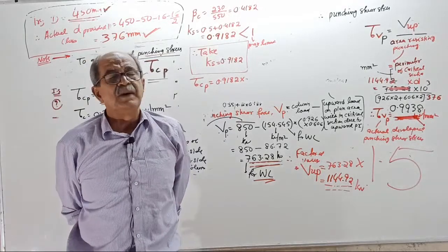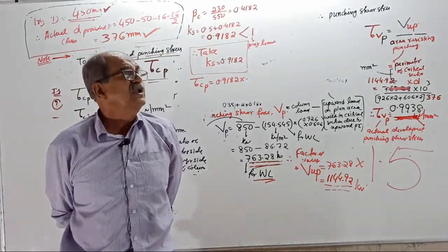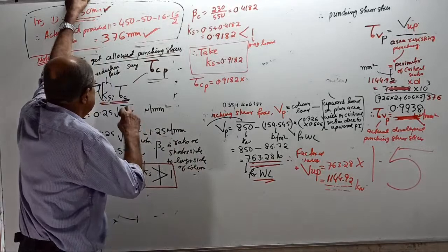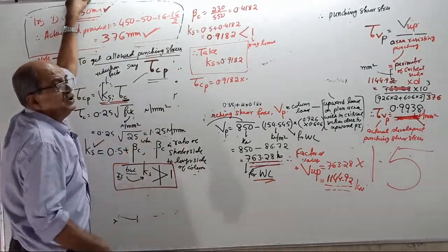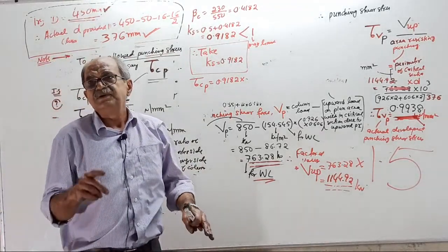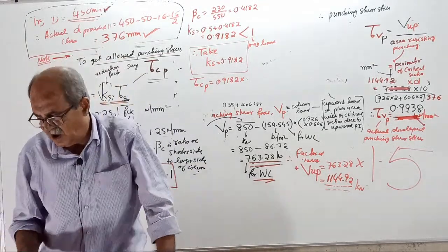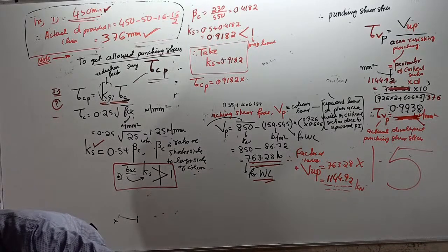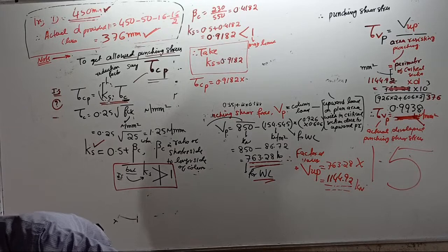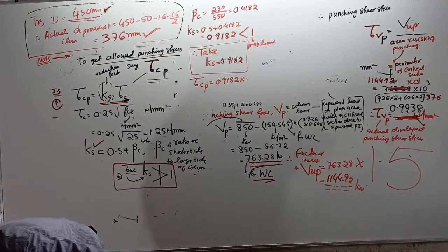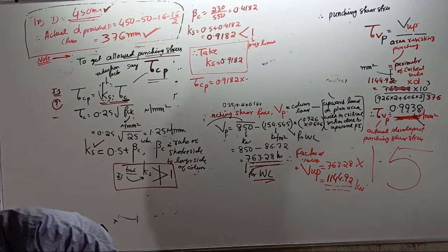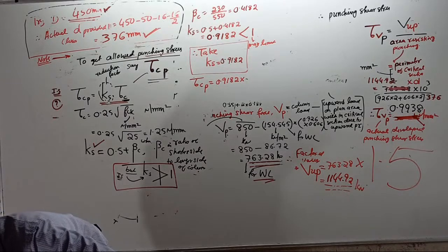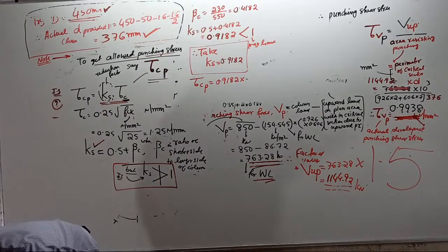By applying the reduction factor, even though the column can resist 1.25, imagine the strength 9% lesser. They want to reduce the strength by 9% for safety because of the non-uniform effect. Because the column is not square or nearly square, it is wide, therefore they are reducing by 9%.